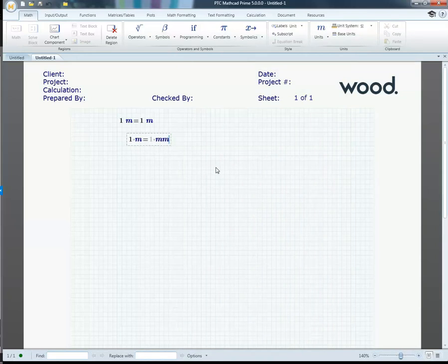And let me type in millimeters. So you can do almost everything from the keyboard. In Mathcad, there's a difference between 1 pound and 1 pound of force. All right. A pound is a mass unit, and a pound force is a force unit. So if you're using the US customary, you need to be careful of that. And most engineering calculations will use pound forces.